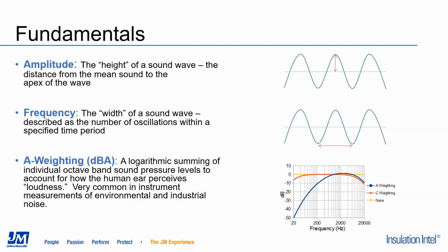So you may have seen on data sheets with equipment that makes noise, there may be a rating in either decibels or a decibel A weighted number. And this is often on handheld sound level meters, if you've ever used those. They often provide an A weighting, sometimes even an unweighted overall level.